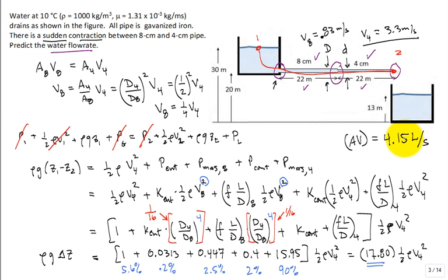Excuse me, Dr. So how about when we did the friction factor, basically we can't estimate the Reynolds number and get velocity. Why do we do a third iteration or fourth iteration? Oh, as soon as you see that it's not changing, you're done. That's how you know you converged. It's not changing. And this will converge even with a fairly poor guess very quickly. In one to two iterations, you can see that you're there. But you really should do a few by hand. You really need to do a few by hand.